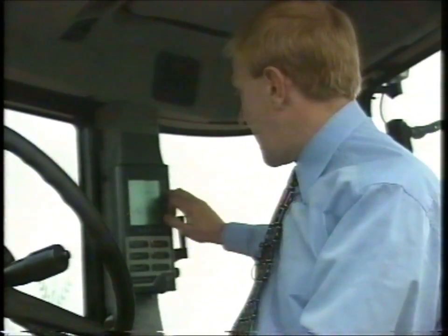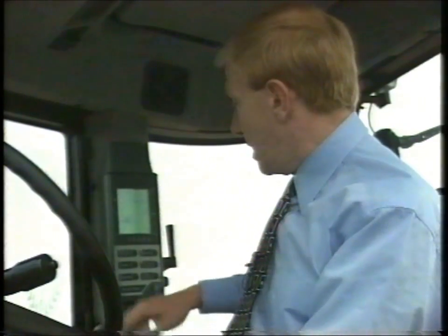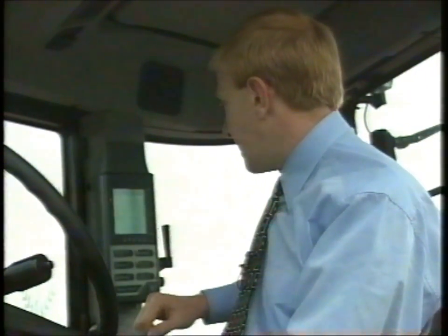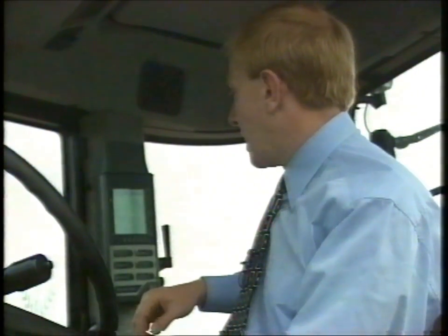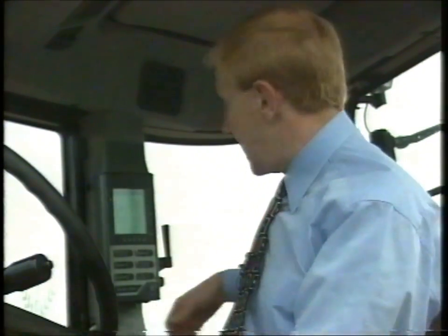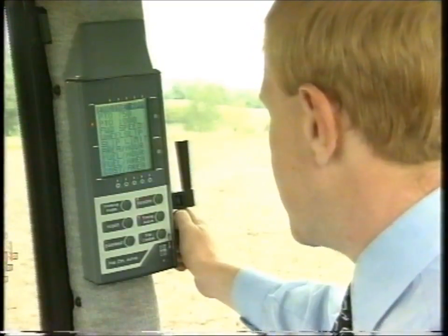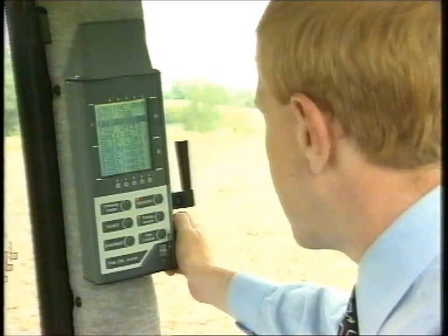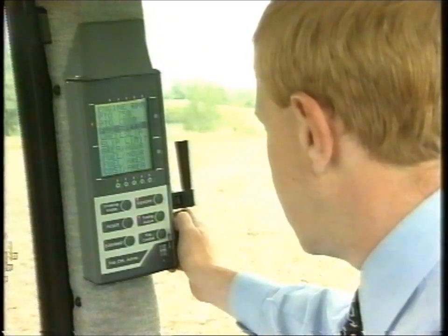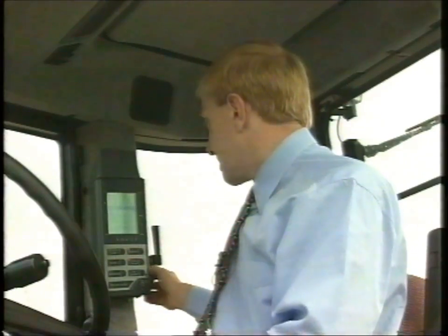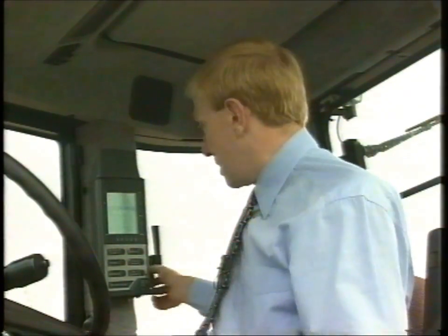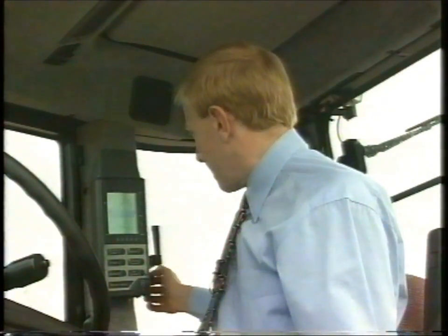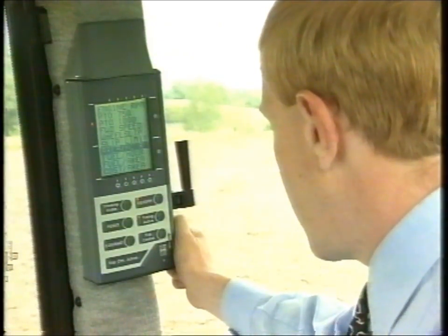First of all, the operator decides which display he wishes to alter and presses the corresponding button. When the LED lights up, he presses the button again, and the display shows all the items available from the main menu. He can then scroll down the menu. Engine speed, economy PTO speed, 1000 RPM PTO speed, forward speed, wheel slip, that's actual wheel slip, slip limit. This can be set anywhere from 0 to 99% in steps of 1%.